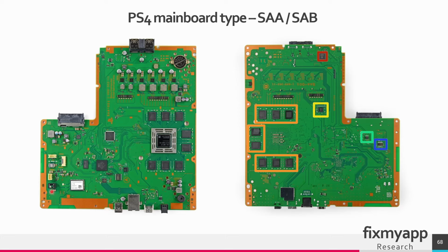This is the layout of it, and as you can see, the circuitry is almost the same. The components are almost the same, only the layout and maybe some refactoring or optimization of the circuit is present. But the big picture here is that you can identify the power phases, the APU, GPU, the RAM modules, the Southbridge, the Bluetooth IC, the power connectors, the SATA drive, buck converters, buzzer circuit. As long as you can identify those components, you can troubleshoot any board.